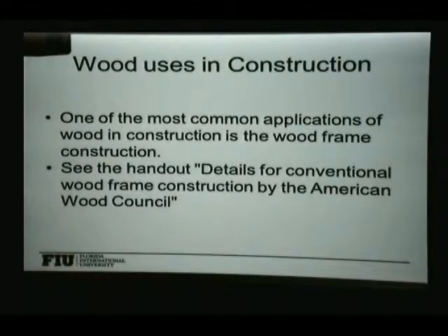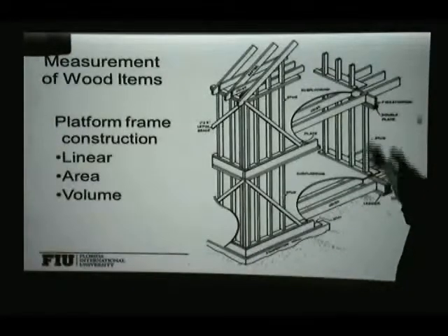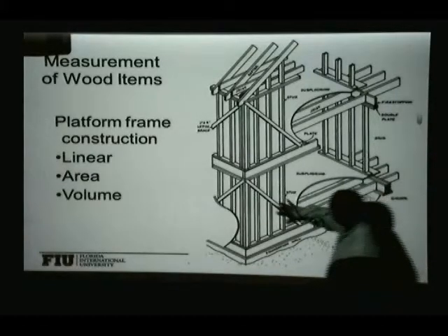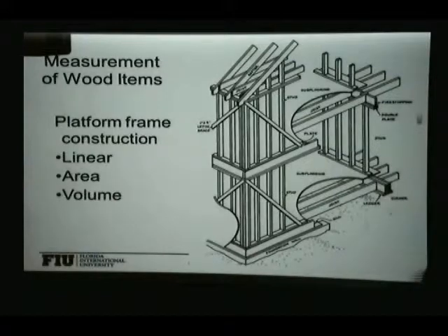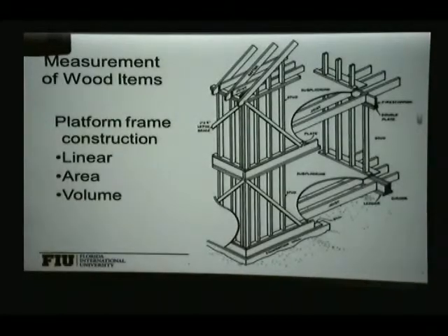In wood, we have wood frames. As I said before, for the roof in our project, we'll have a wood frame roof. So we need to identify all the different elements that support that roof structure. If you go up north, the actual walls of the building are normally made out of wood also, with plywood and sheeting to prevent water intrusion. So here in Florida, we normally have masonry walls, and then we may have the wood structure of the roof. So it depends on where you go, you will find different uses.